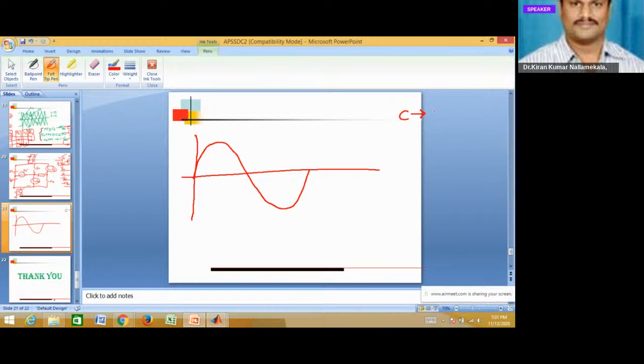That is equal to the number of levels minus 1. So it is a 5 level inverter, so you need 4 carrier signals. For a 7 level inverter, you need 6 carrier signals. As it is a 5 level inverter, we divide the regions into 4 different regions.